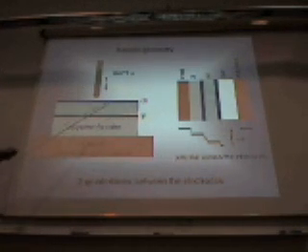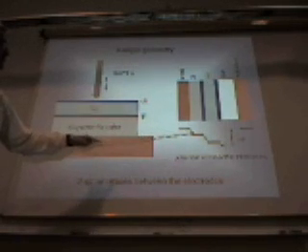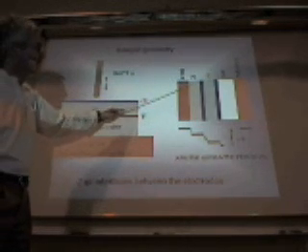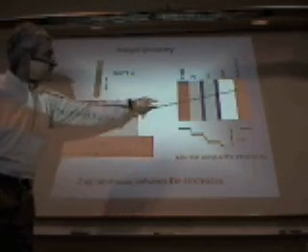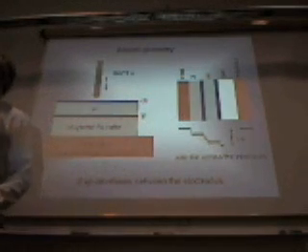Now, when you look at the potential across this whole stack of layers or materials, you might be looking at just a sketch somewhat like that. So the electric potential across this interface may fall. Then you have an interface between the silicon or silicon dioxide and the quasi-liquid, then the quasi-liquid and the ice, and so on. Then there's the gas phase, and there's the reference electrode. And what you measure is the sum of all these changes as a sum signal, which is giving you this difference. That's the work function you measure. So you don't see these individual steps and jumps. You just see the combined action of all these.